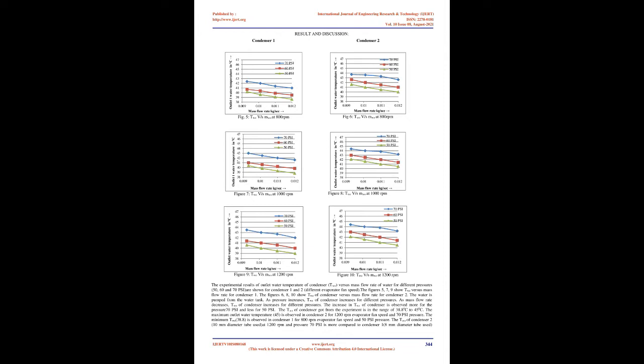Experimental procedure. The experiment was conducted to measure the rate of increase in water outlet temperature in the condenser at different pressures and mass flow rates. Refrigerant is filled to a pressure of 50, 60, and 70 psi into the heat pump model at different intervals. Initial reading at 50 psi filling pressure. Both pressures and temperatures in the gauges are noted and the inlet water temperature of the condenser is also noted. The heat pump is started and allowed to run for some time to reach steady state.